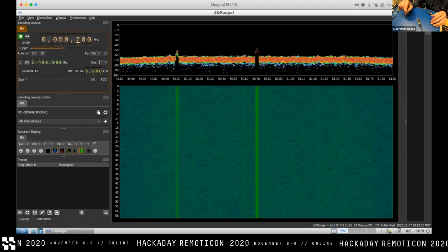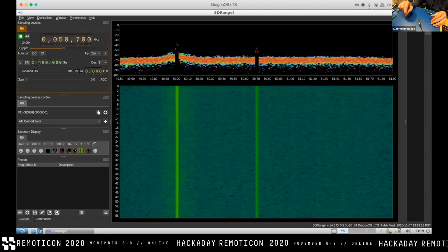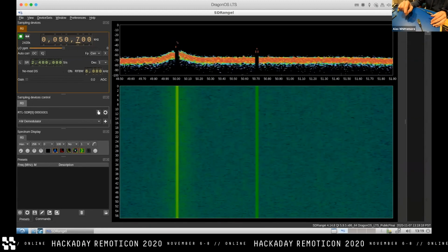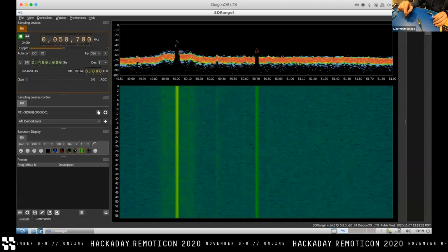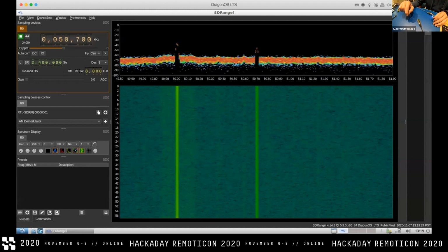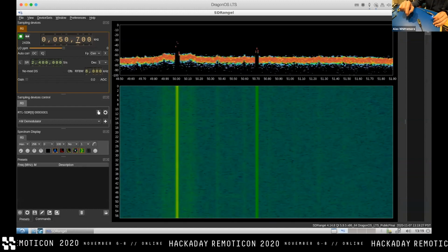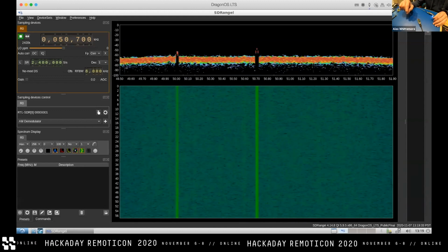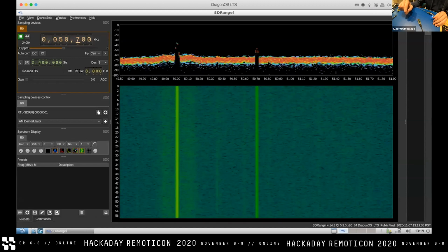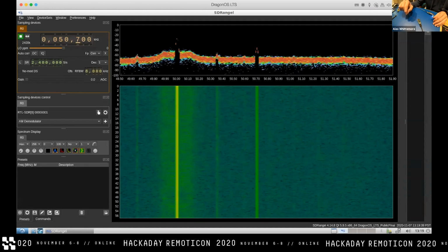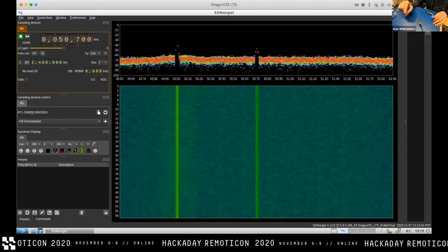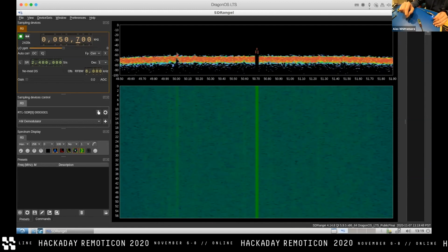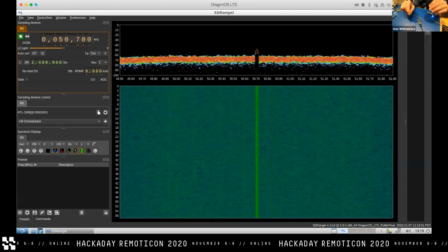It looks like it's not down at this end of the board, but it's a little bit tough to say. It's getting hotter. It's getting hotter over here. That's interesting. Okay, so it's getting kind of hot in this area of the board, like centered over the BX. If we move over to the other side, it's still pretty hot. I don't know. It's definitely somewhere up on that top half of the board, and definitely less obvious down here. Definitely not the far corner of the board, so it's probably not this SPI flash device. It might be the FPGA itself, but I'm not really sure. It's probably not the USB, because 50 megahertz doesn't make a ton of sense, and obviously as soon as we get up the cable, the shielding, no, it's definitely not that. So it's somewhere around here.